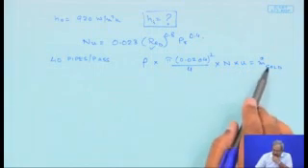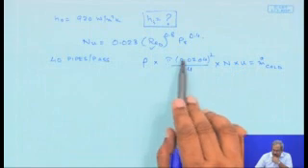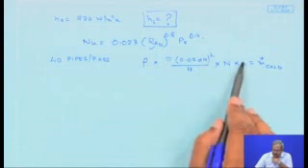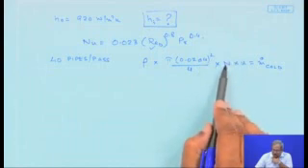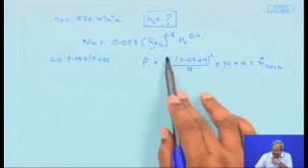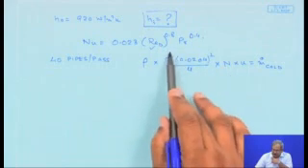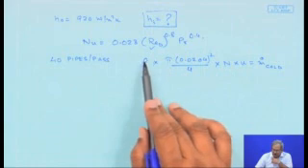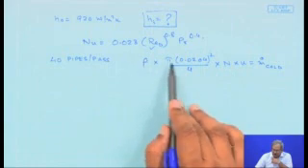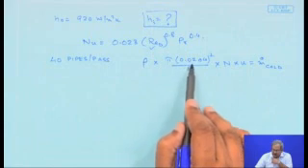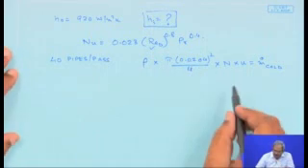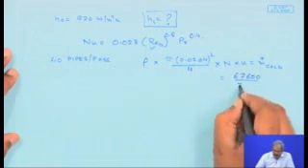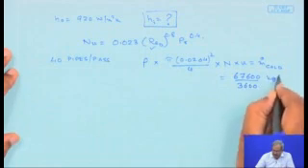Once again, the mass flow rate of the cold fluid can be calculated based on the cross sectional area multiplied by u, which would give me the volumetric flow rate through one tube, multiplied with n, the number of tubes per pass. This is going to be the volumetric flow rate of the cold fluid entering into the heat exchanger. When I multiply it with rho, this becomes the mass flow rate of the cold fluid entering into the shell and tube heat exchanger. And this we know to be equal to 67,600 by 3600 kg per second.